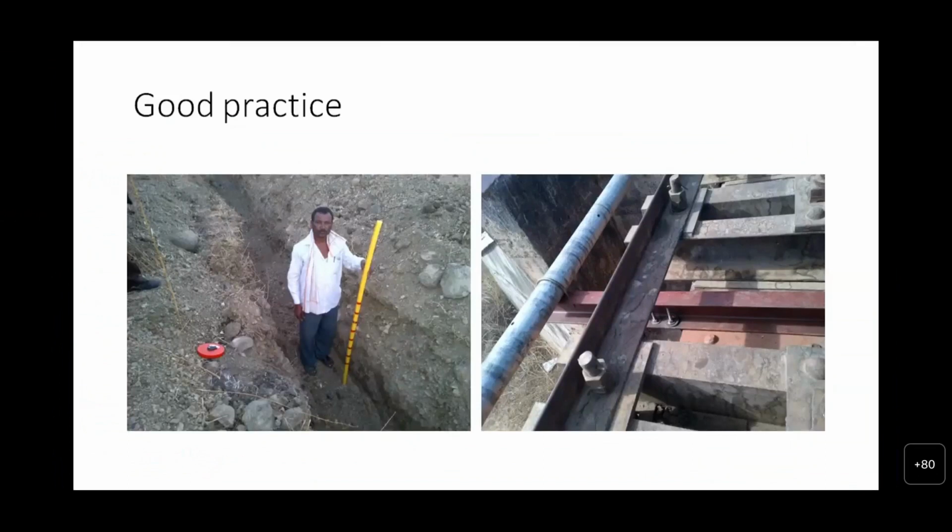So before laying the cable, the trench can be measured with a stick, which can properly indicate the depth: the 1 meter indication, 1.2 meter indication, and 0.8 meters. A strip has been pasted on that stick. So one person can just walk along the trench so that we can easily make out whether the depth of the trench is 1 meter or less than 1 meter.